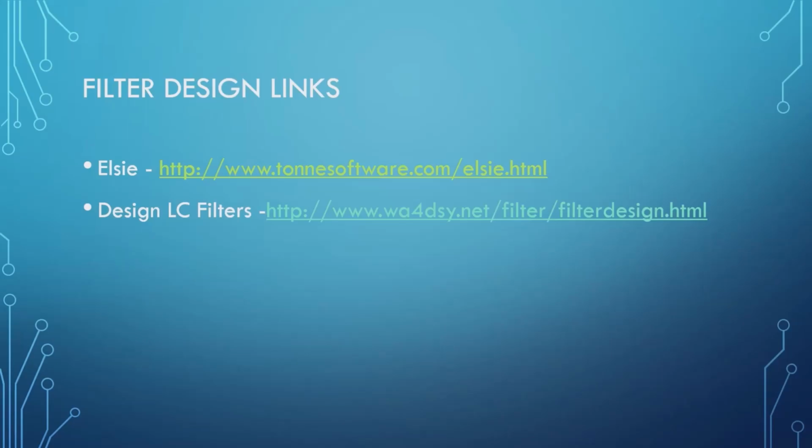You can actually, and I don't. Go ahead, Roger. Excel has a great function called Solver, where you can set up one equation for your L, your inductor, and one for your capacitor, and set a value, a goal in L, and have it solve for the most efficient C for our resonance. So you give it a goal, and it'll sit there and iteratively solve the equation, even complex ones. So very useful.